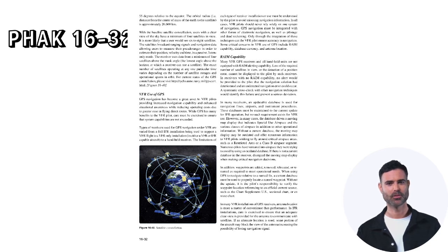In many receivers, an updatable database is used for navigation fixes, airports, and instrument procedures. These databases must be maintained to the current update for IFR operation, but no such requirement exists for VFR use. However, in many cases, the database drives a moving map display that indicates special use airspace and the various classes of airspace in addition to other operational information.